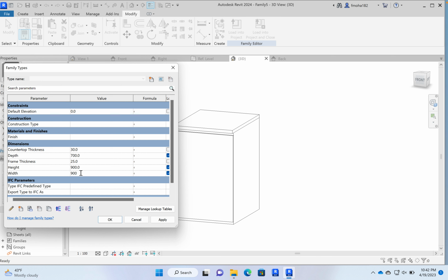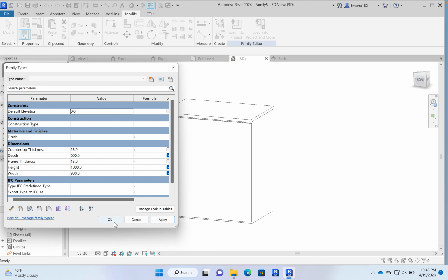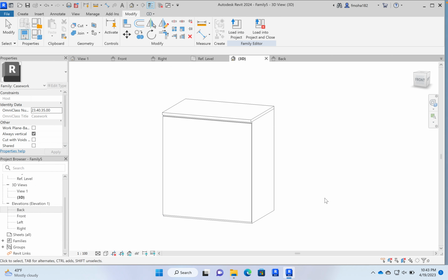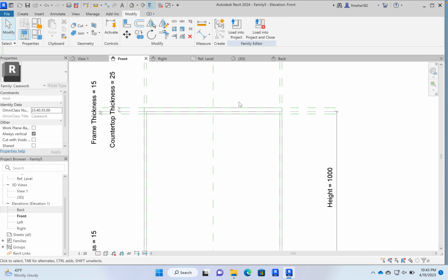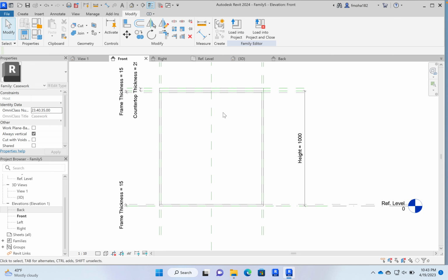So we go back to our normal sizes right here. Example 25. Change everything, we go back. Now that I want to make a void part right here, I want it to be parametric as well. So I'm going to go to the front section right here, the plane that I'm going to work on, and then I'm going to create some new reference planes.